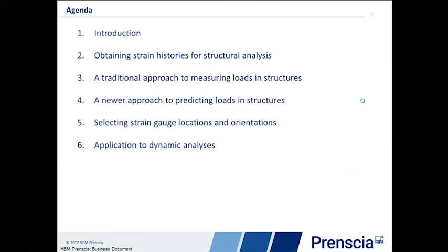Today we're going to talk about loads reconstruction, and we're going to go through a brief introduction on the goals for basically early design and then the need for loads in doing those analyses. We'll look at ways to recover loads traditionally and then look at the loads reconstruction using measured strains. We'll talk a little bit about strain gauge placement in terms of placing gauges at ideal locations, and then we'll finish up looking at the application of loads reconstruction in dynamic analyses.